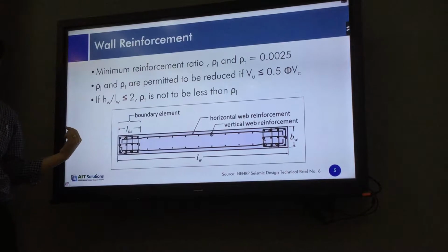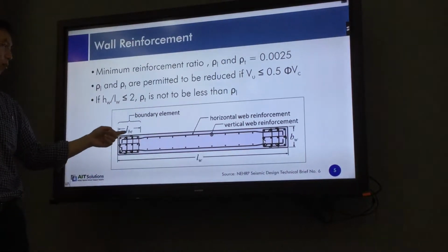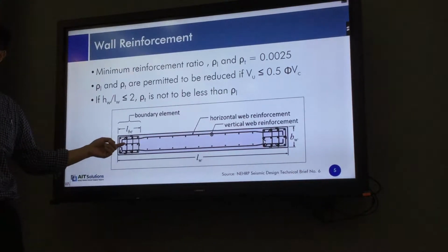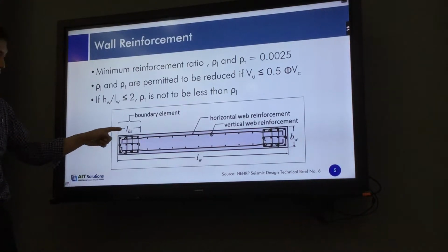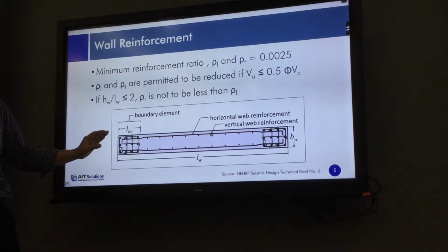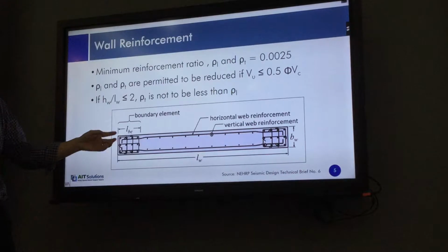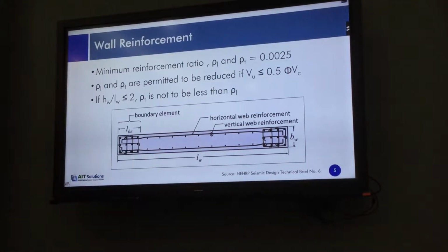But for earthquake loading, this will be cyclic, so this side will have both tension and compression. This confinement is especially for the compressive stresses. If large compressive stress occurs, the concrete is brittle, so if we provide good confinement, it will become more ductile.